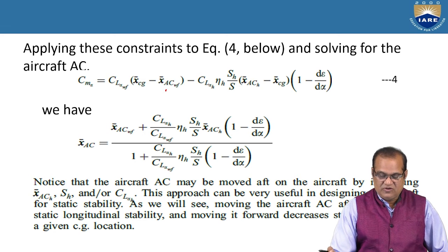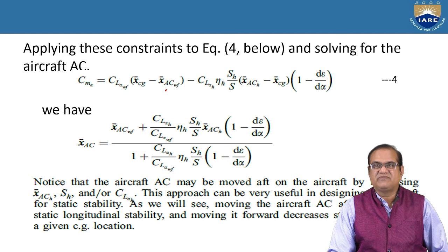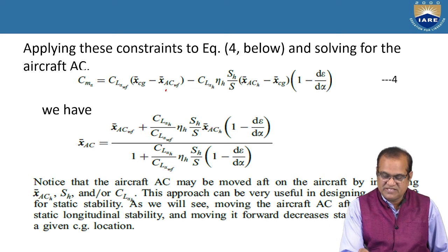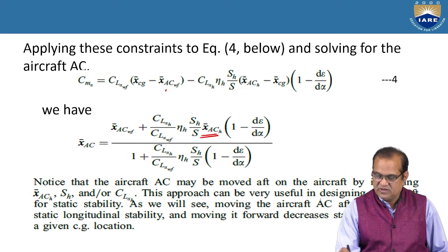If you want the aircraft AC to be moved aft, you can do it by increasing this value here. If we increase this value, XAC will be going aft.